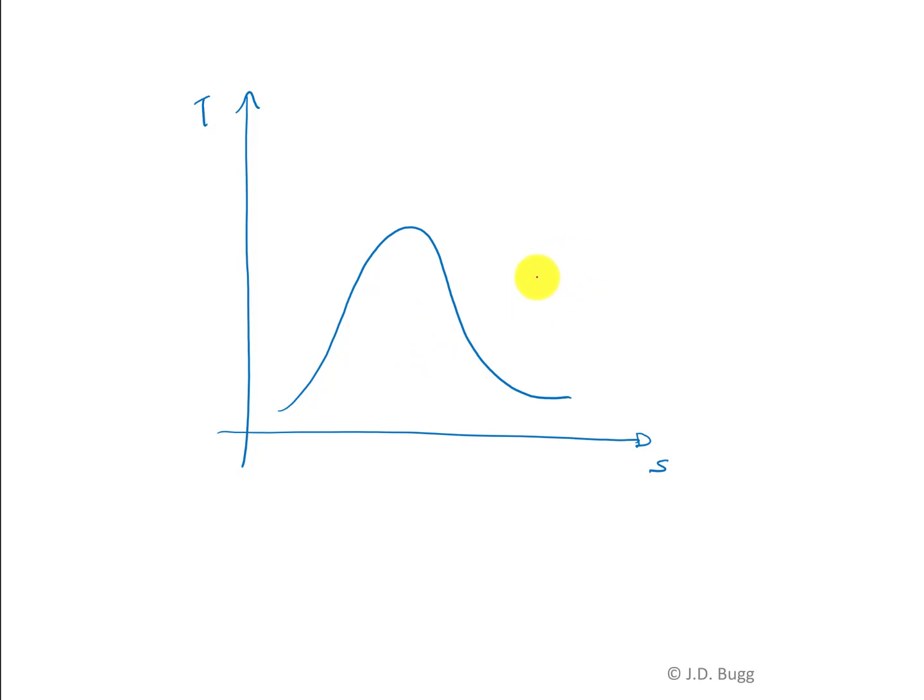The condenser pressure will be a relatively low pressure down here at 10 kPa, so that's a horizontal line inside the liquid-vapor region, and it angles up like this. So that's our 10 kPa, the condenser pressure. And the steam generator pressure is a relatively high pressure, so I'll show that up here, and that's 10 megapascals. In the liquid region, these lines actually go down almost perfectly on top of the saturated liquid line, but typically we show a little bit of separation there just so we can see what's going on in that liquid region a little bit easier.